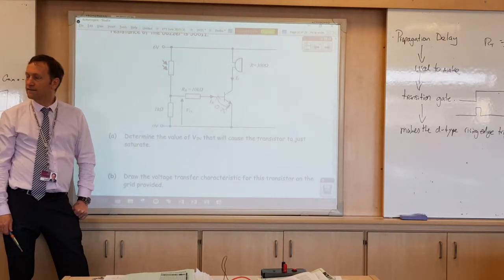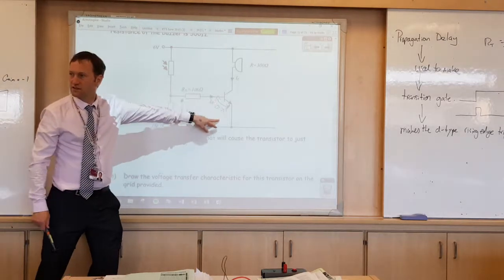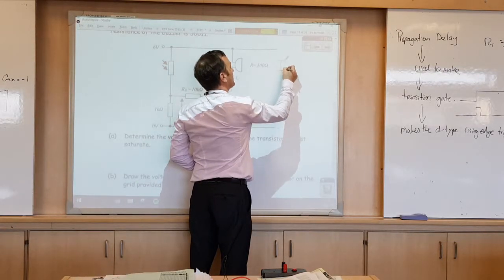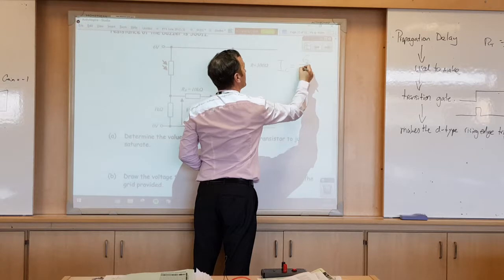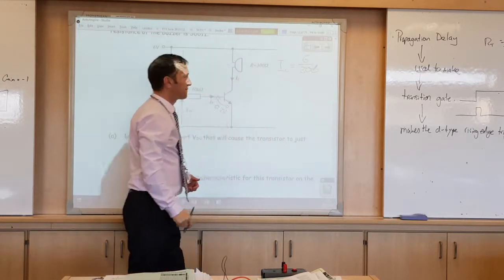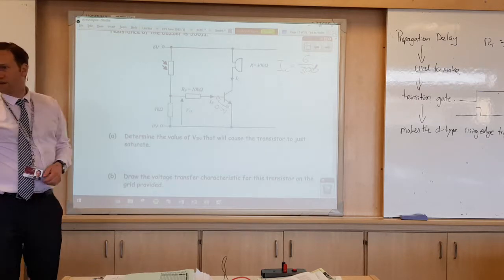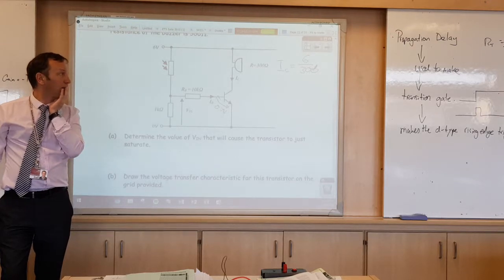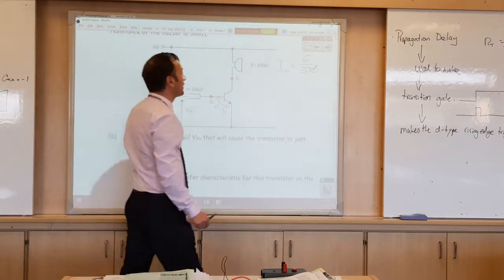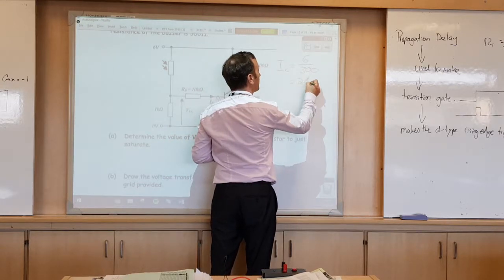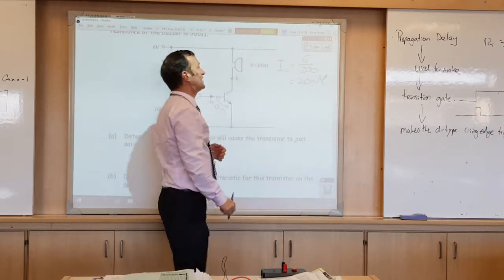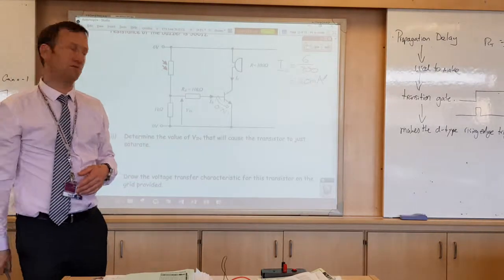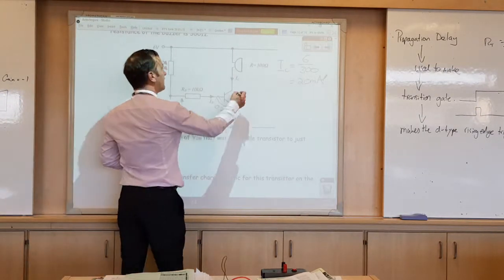Is it Ohm's law to find IC? Yes, so sometimes you have to work that out first. So we've got IC equals 6 divided by 300. Okay, we know that. So what's 6 divided by 300? Is that 50 milliamps by any chance? It's 20 milliamps. So we've only got a little incy current that runs a buzzer anyway. It's hardly like this thing with 3,400 milliamps. So we've got 20 milliamps going down here.